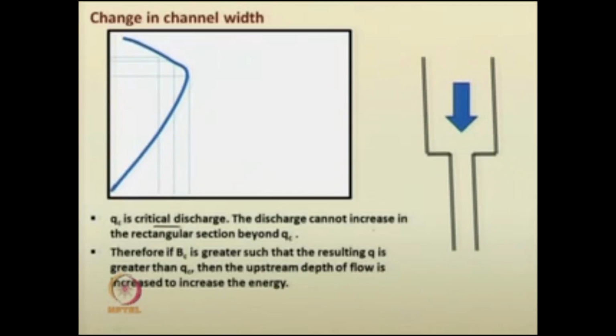The discharge cannot increase in the rectangular section beyond the qc value. Therefore, if the constricted width B is smaller than Bc, so that q becomes greater than qc, that is not theoretically possible.